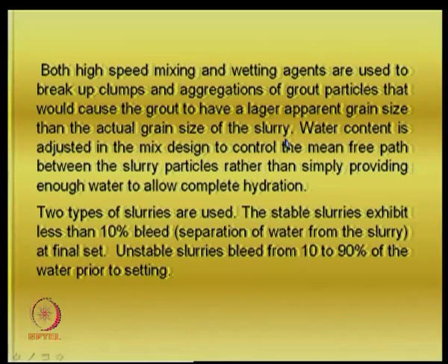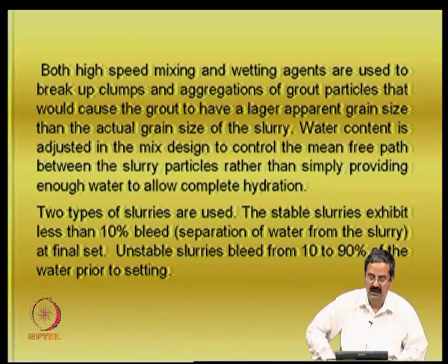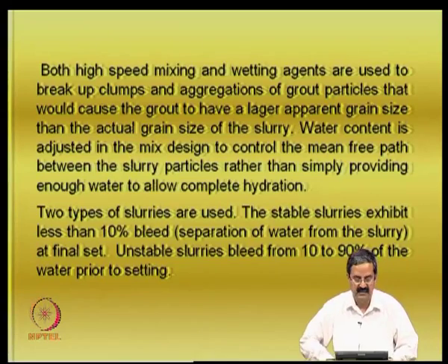So, we try to use agents so that clumps or aggregations are not there, and water content is adjusted in the mix design to control the mean free path between the slurry particles.